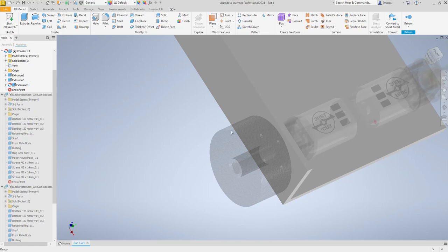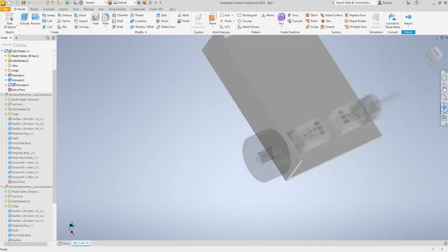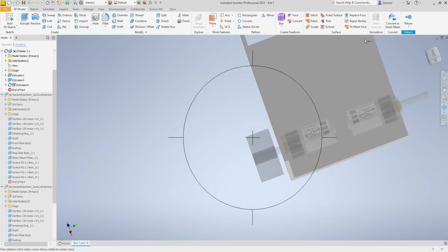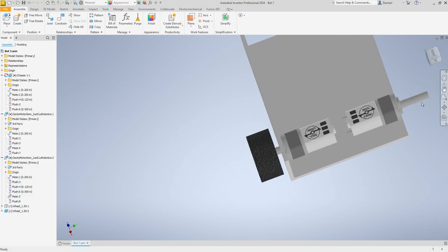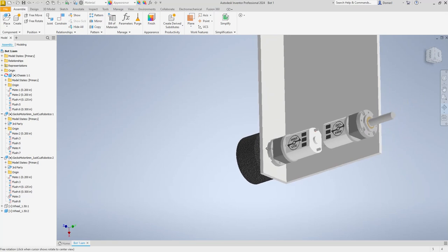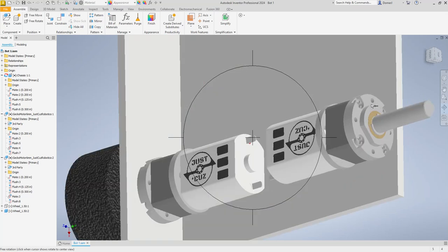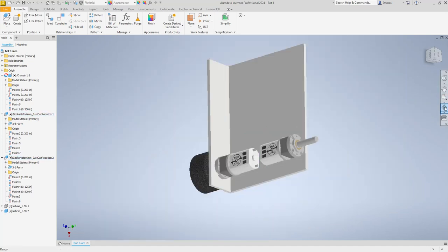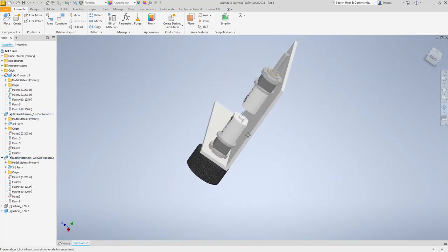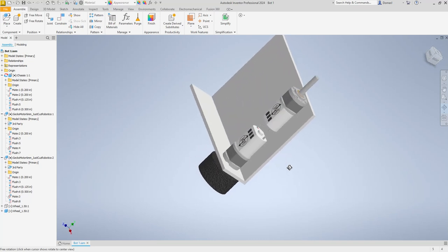Now there's some other things about that setup. If we take a look at that motor, so let's go ahead and finish, return. If we look at that motor, there is a flange right there. So I could also extrude cut that flange into the sidewall, so this actually sits flush if I wanted to. And I need a hole for the axle to stick out as well. So there'd still have to be some more geometry done to that wall for the motor, but essentially what I just did was lock that motor into that wall. So that's pretty cool. It's one way to do it.